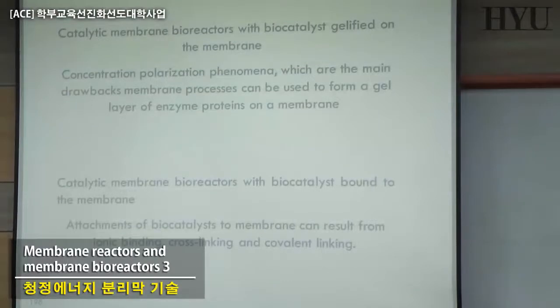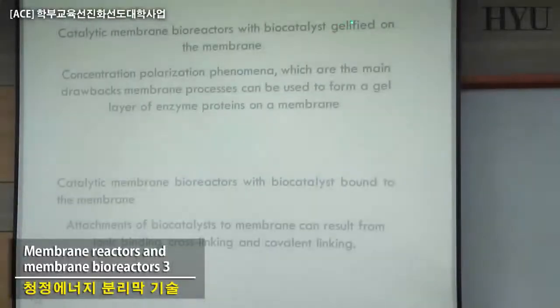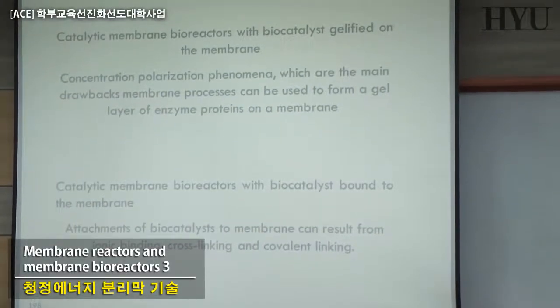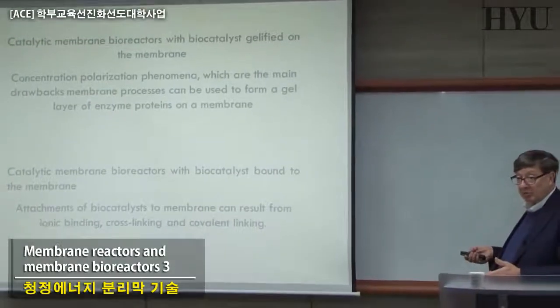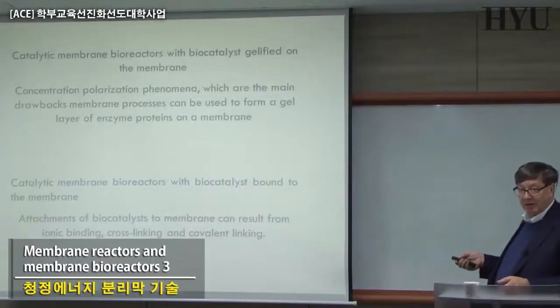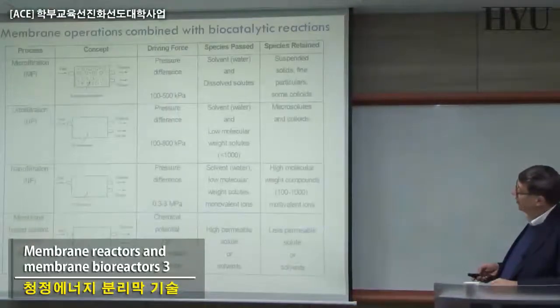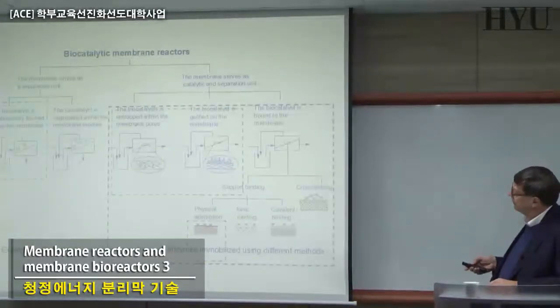That is the one thing I was already mentioning that has been studied. You can also try to take advantage of the concentration polarization I was mentioning before. You can gellify: you can arrive at a certain level of concentration of your protein and just go from a solution to a gel. The gel can be just an additional layer on the membrane, but gels are relatively permeable, and so you can have a gelled immobilized enzyme reactor, dynamically formed eventually. So there are different formulations that you can study, and there is a lot of this kind of operation that can be utilized.